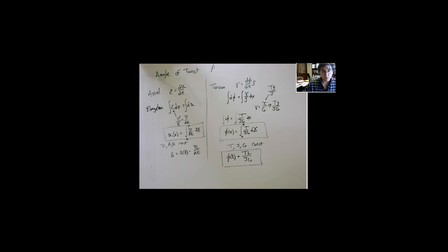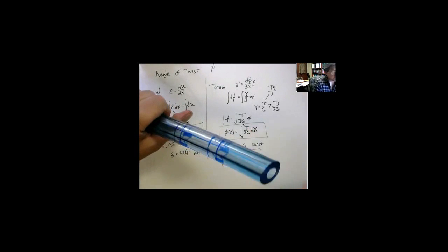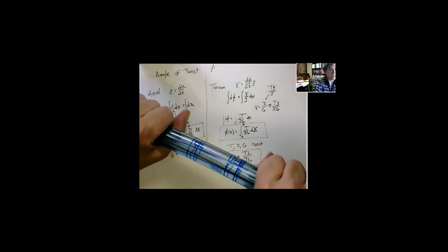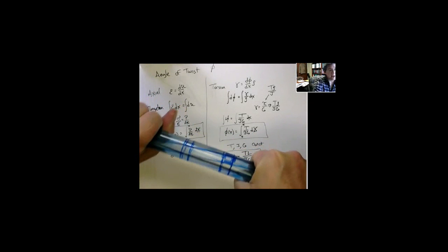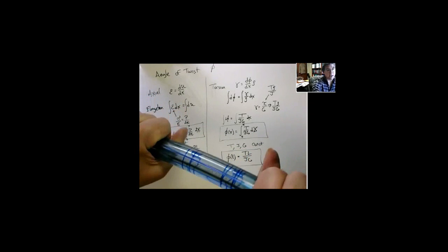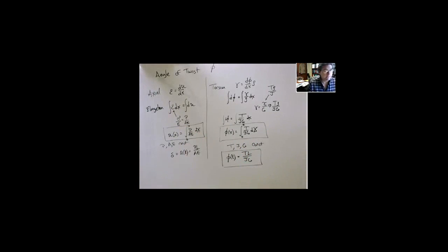Okay? So this will tell me if I have a section here that has constant cross-sectional area and the same material, so G is constant, J is constant, and if we put torques at the ends, that means the internal reaction torque is constant all along the section, no change. That means we can figure out the angular twist. The front hand moves relative to my back hand, and that is T L over J G. Okay? That's it. Pretty easy. I think in general for a lot of this stuff, you see the same with bending. If you keep straight the analogies with axial, it's